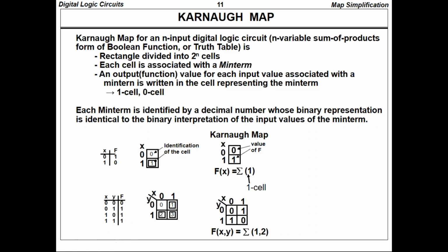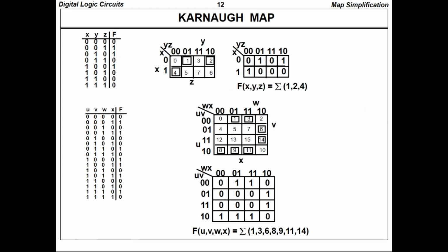So likewise we are simplifying that expression. Here is an example of some form of K-map. Here you are having 3 variables x, y, z, and the x variable is 0, 1, and here 0, 0, 0, 1, 1, 1, 1, 0. So this is in the form of gray code order.